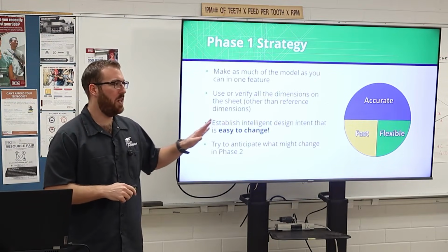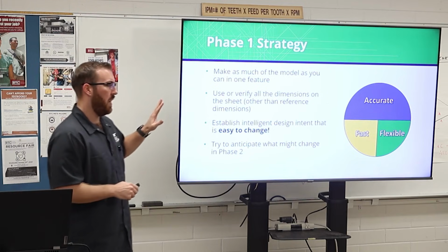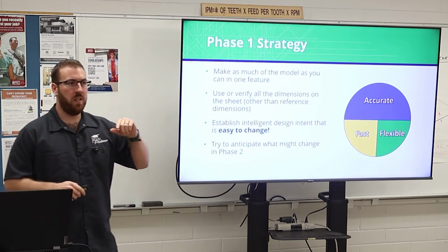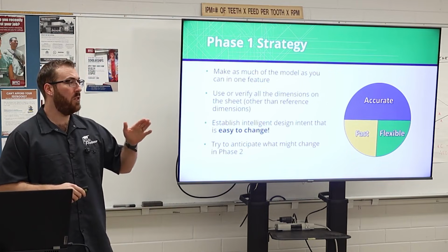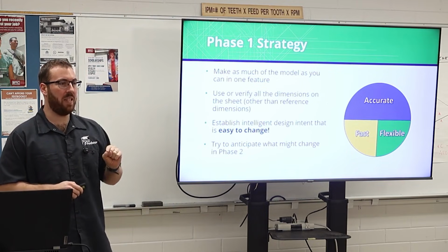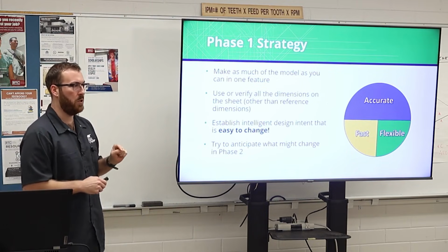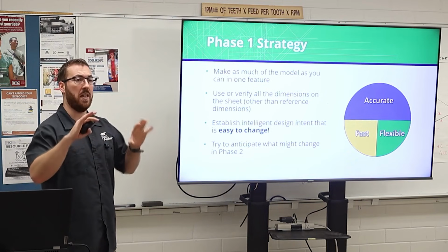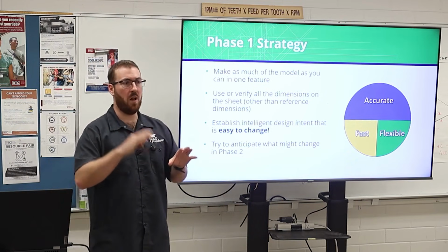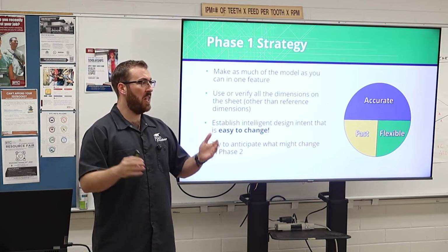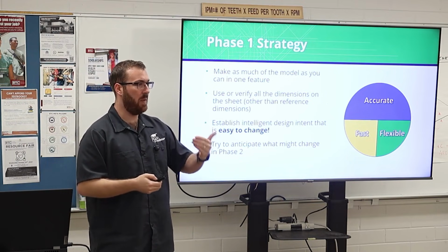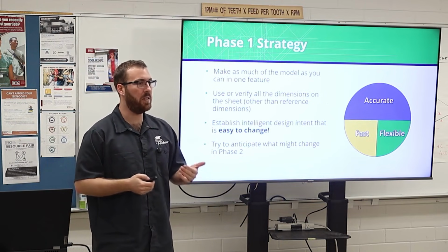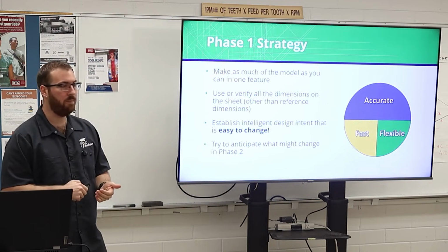I will also add one additional note here. When you look at a drawing, just because a dimension is associated with one certain view doesn't mean that's where you have to sketch it. I think this trips up new users too. You may see a dimension that is illustrated on the right view, but when you're sketching it, you can include it on the front view to make things more efficient for you. And that's something worth keeping in mind here.